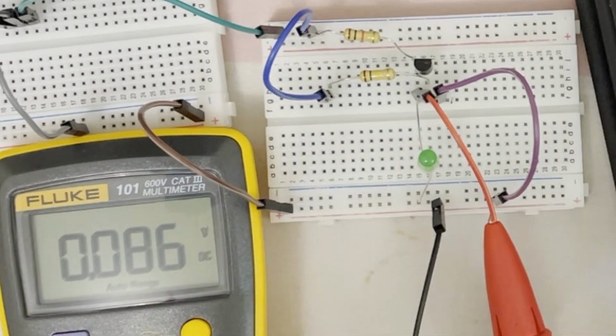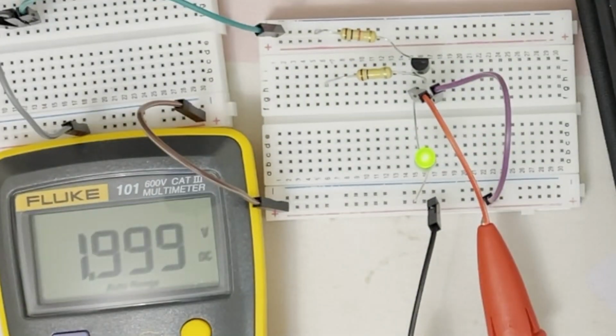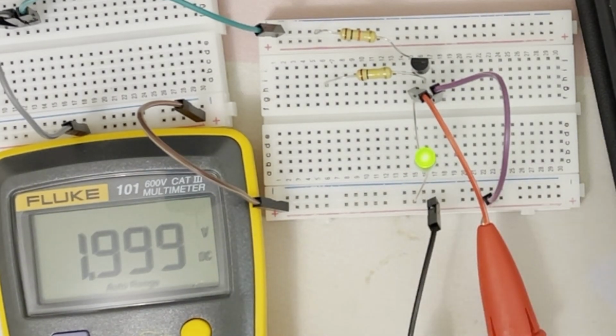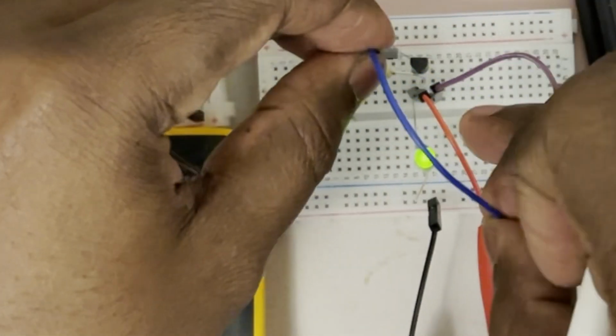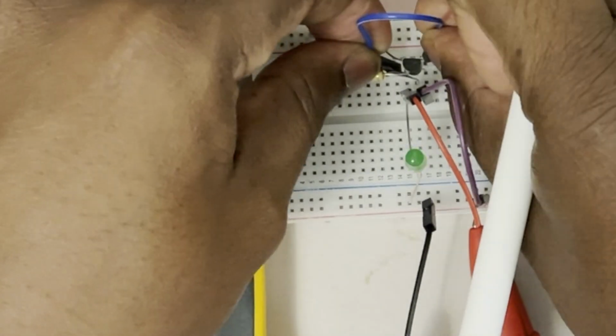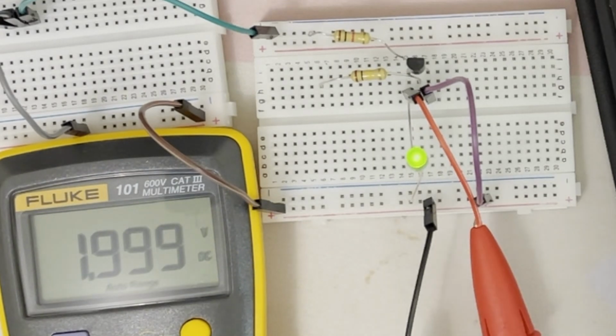Okay, so for the troubleshooting of this one, first what you need to check, here when you do the circuit diagram, at that time you already saw that the LED is turned on if I remove this one. Okay, if you saw that the LED is not turned on, then what can happen, if I just short collector and emitter of this transistor, you can see LED is turned off. What I did, I just short collector and emitter. That means if the transistor is burned, if the collector emitter is short in the transistor, then LED will be turned off. This is the first troubleshooting.